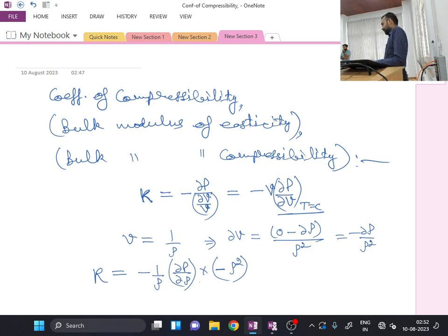So isothermal and adiabatic conditions are different. Even if you have a heat transfer situation, if you are adding heat to a system and rejecting heat out of the system at the same rate, in terms of work or heat transfer only, then also the temperature will remain constant. So for an isothermal condition to be maintained, it does not always have to be adiabatic. It is not at all required.